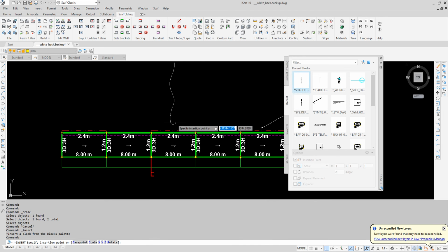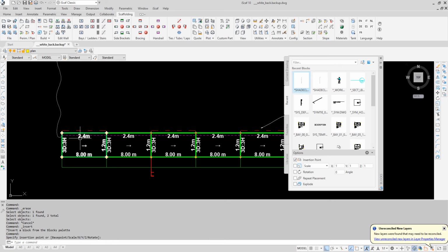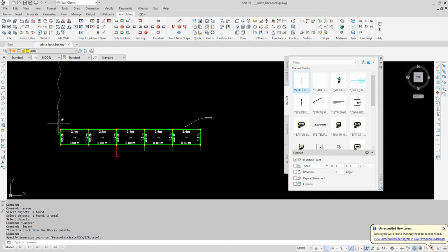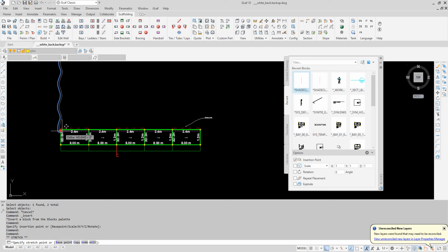So this is the part that's a little bit tricky. You can move the shade cloth anywhere you want. And I want to just drop it down here, and I want to rotate it. So I've clicked on there to drop that shade cloth down. I click on the actual shade cloth again. Let's zoom out a bit. Click on the shade cloth. We have that little blue dot there. We'll click on the blue dot, and then we can specify what we want to change.